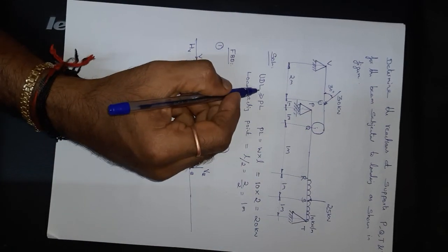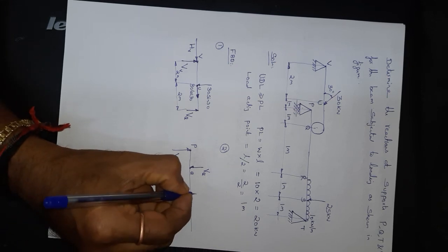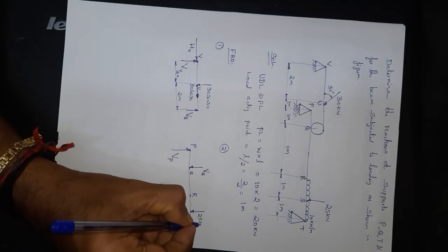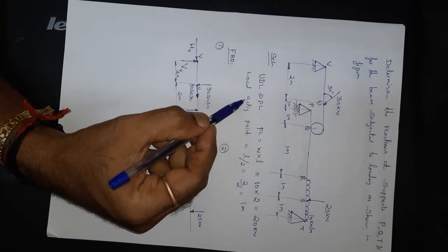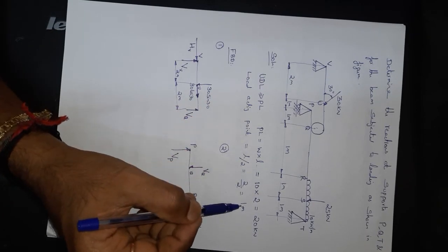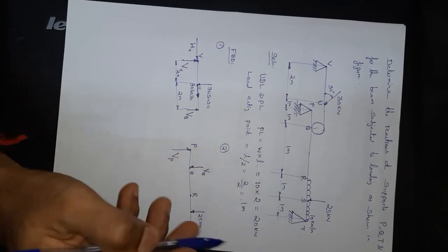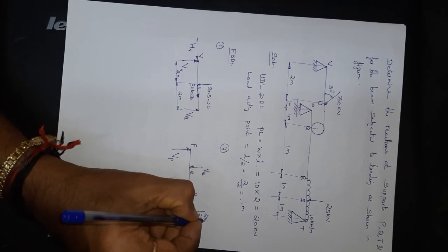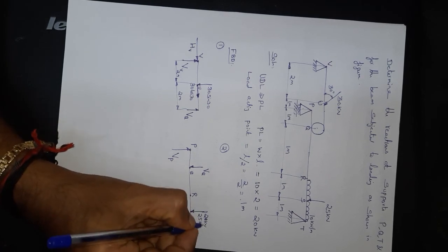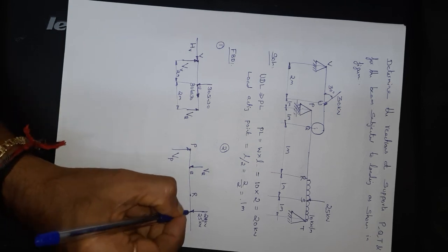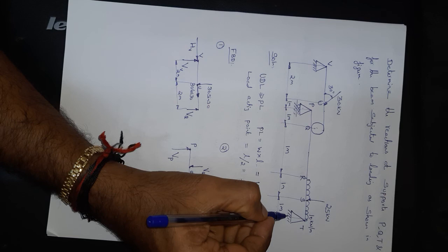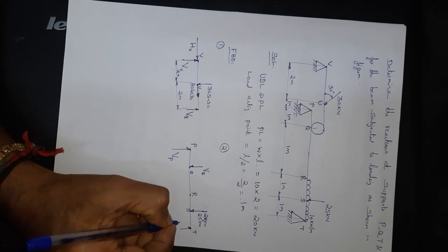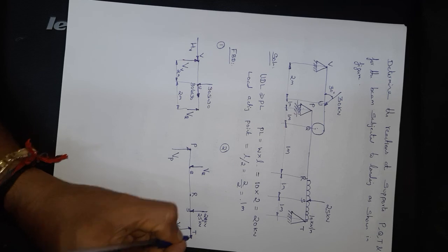And the UDL has been converted into a point load, right? So this is R, and at S, there is a load which is acting, that is 25 kilonewton. Got it? And look at this, the UDL has been converted into a point load, which is acting at 1 meter from R. So this can be mentioned as already, it is 20 kilonewton, plus this 25 kilonewton. And at point T, a hinge support or pin joint support, which will have one vertical reaction, that is VT, and a horizontal reaction too, that is HT.